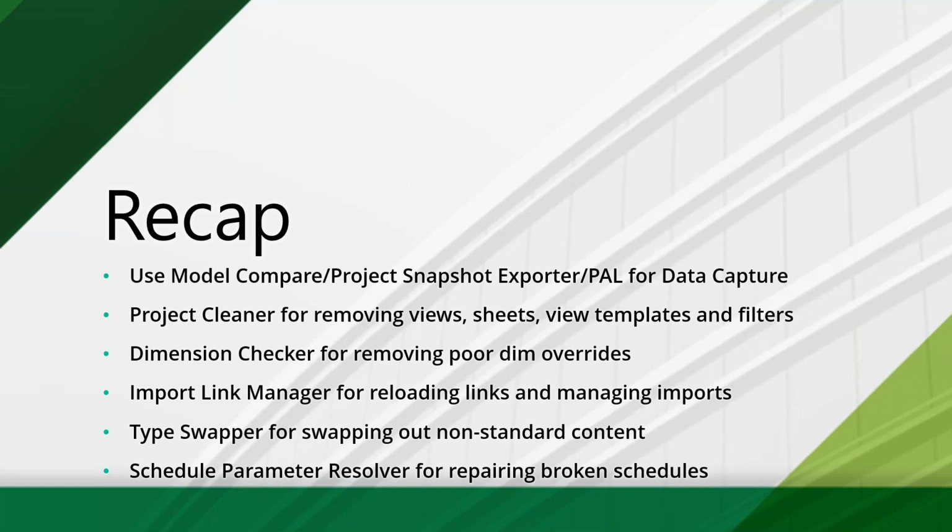In week 2, we talked about, once we figured out what the issue was, let's clean it up. So we have Project Cleaner for purging views, sheets, schedules, line types and patterns, maybe from an exploded AutoCAD file, blowing all that stuff away.